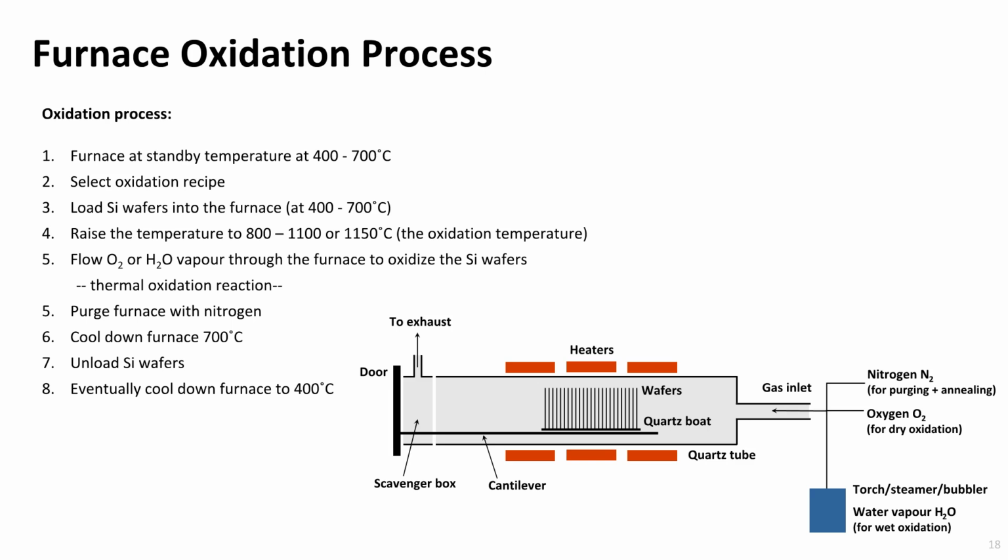Once the oxidation is completed, the furnace tube is purged with nitrogen to stop the oxidation reaction and to anneal the wafers. The annealing step improves the oxide density and thereby the quality of the oxide film. It can repair some defects within the crystal structure and reduce some vacancies and dislocations at the grain boundaries. A nitrogen annealing step is an inherent part of each thermal oxidation recipe at DTU Nanolab.